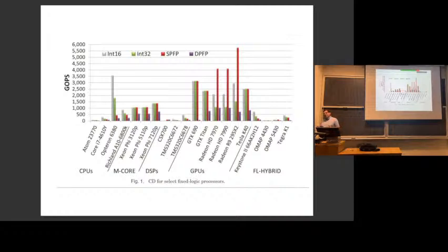These GPUs are a few years old. If you did this again on a very recent GPU, 16-bit operands will usually get higher performance because they now split the data path for 16-bit operands. And the reason is machine learning. For graphics, they really wanted single precision floating point. They didn't really care very much about things like 16-bit integer or weird 16-bit floating point operations.